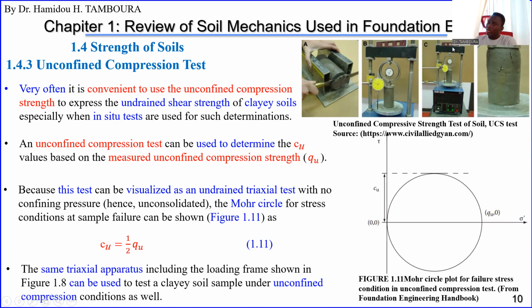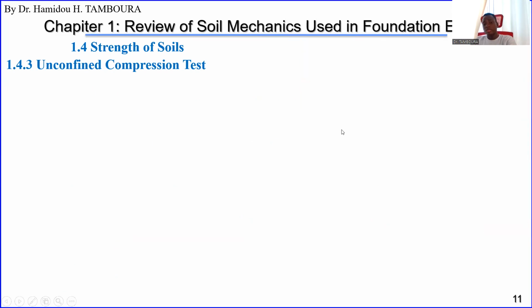Don't forget that you are applying force on the sample, so you need the pressure, the stress. You have to do the force divided by the cross section of your soil sample. But the problem here is that the cross section of the soil sample is changing when you are doing the compression, so it has to be corrected.